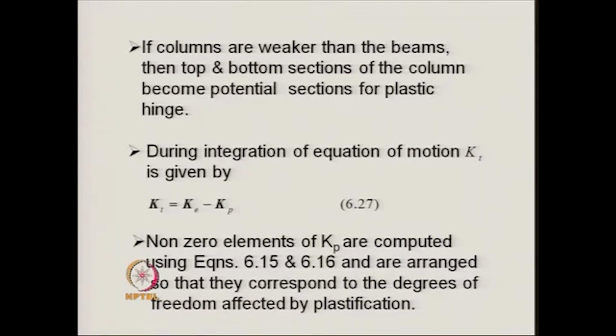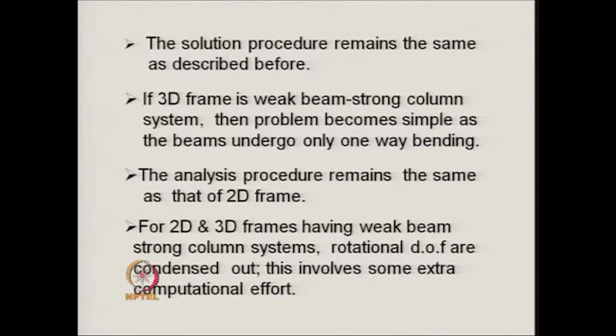Therefore, what is generally done is that at the yielded sections, the associated degrees of freedom are arranged accordingly in the entire sequence of the degrees of freedom. Then the solution procedure remains exactly the same as before.